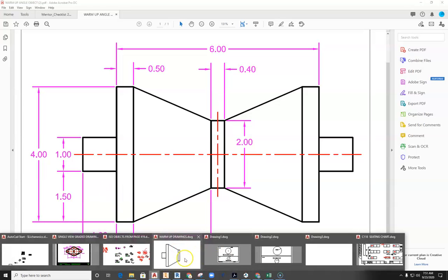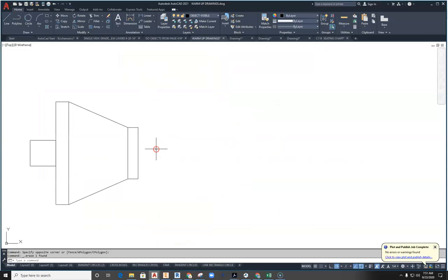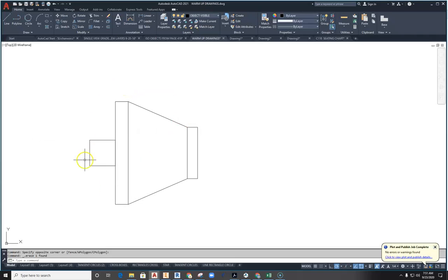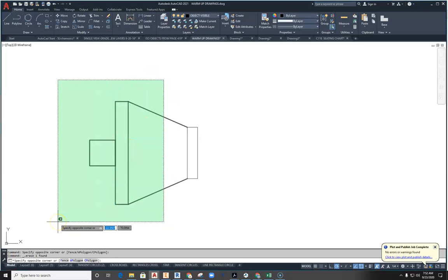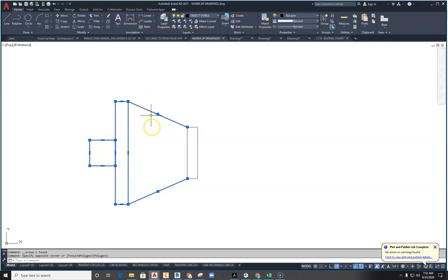And in CAD terms, I've got a whole lot more complete, because the next thing I'm going to do is use the mirror command. All right, so to use this command, it's up here on the ribbon bar. But first, I want to select what I want to mirror, because I want you to get used to selecting what you're going to mirror first. So I want to mirror all this stuff.